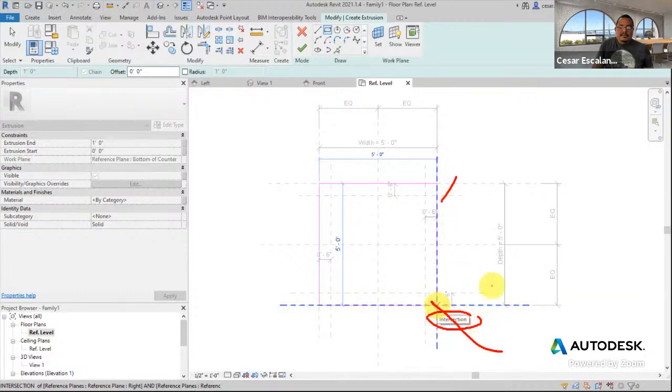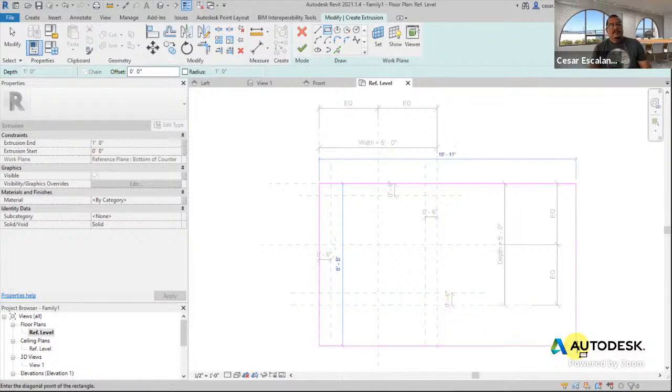And then you see these two things in blue. When a sketch line snaps to point intersection, it creates an automatic lock with this work plane. And that's what you're going after. You want this sketch line to always be aligned with the edges of the table.